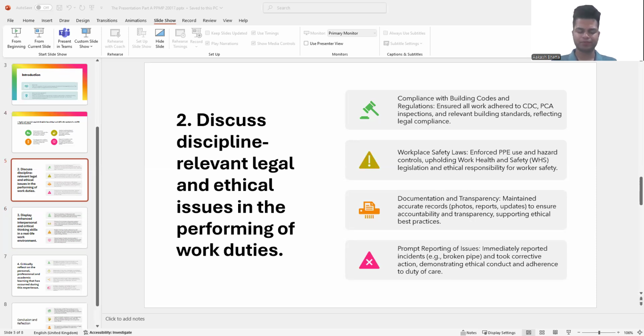We had to get PCA and CDC before starting any demolition or construction works. We had to get the compliance development certificate, and even for stormwater easement and for plumbing works, we needed approvals before excavating. There's a thing called Dial Before You Dig, so we check if there are any service lines running underneath our building. Before excavation, we need to make sure of that.